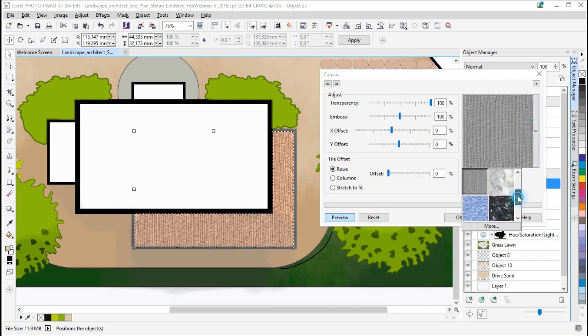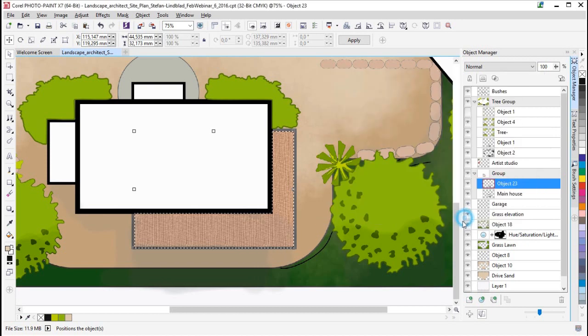You have a selection of already pre-installed effects, and many times these are perfectly okay for many effects, and they've been around for a while, but you can always use some of your own images that you want to add through this dialog, or doing it differently. But this way it's very easy to just change, in this case, just the emboss a little bit. As I change the emboss, you see how it affects the texture here. So less emboss, and it softened the feel. And then click OK, and then deselect the selection. So suddenly I have a nice texture to the terrace.